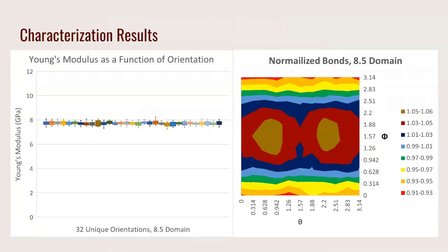After analyzing all the data, we can confirm that there was mechanical and geometrical isotropy. As the domain size increases, more particles are generated and packed in, which reduces the influence of local imperfections, resulting in lower variance in the data. One big note is that there's little change in geometric isotropy depending on the domain size compared to mechanical isotropy. This indicates that the domain does not contain crystallized regions. It also illustrates the importance of quantifying mechanical isotropy in addition to geometric isotropy, as significantly fewer particles are required for a domain to be geometrically isotropic.